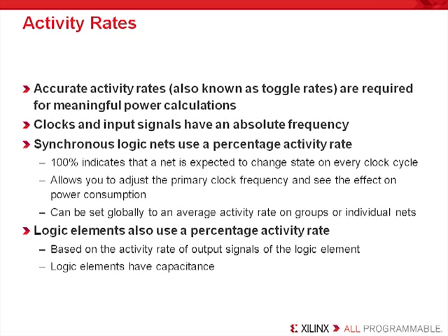An activity rate is a percentage of the time on each clock edge you expect the component to toggle. That means if you expect it to toggle on every clock, like the least significant bit of a counter, then its activity rate will be about 100%. Likewise, the most significant bit of a 16-bit counter won't toggle much at all and can be ignored. Now, this will vary by design, but only you know your design well enough to estimate your system activity rates. Just don't ignore the activity rates and only work with the default activity rates. Try to spend some time estimating your activity rates, at least on a component basis. That way your estimate is as accurate as it possibly can be.